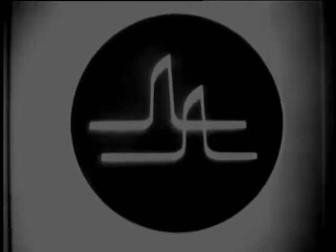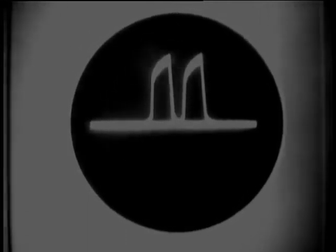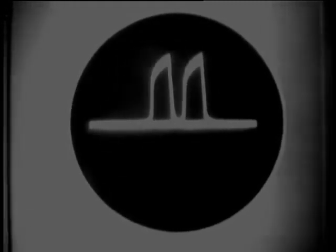Normally, the two baselines are superimposed and appear like this. But there are still two separate baselines and two pips. On the actual scope, you may see them like this, and by adjusting your spread control, you can govern the distance between them. So now you know that by switching a single lobe back and forth often enough, we can get the effect of two lobes and thus stay on target much more accurately.